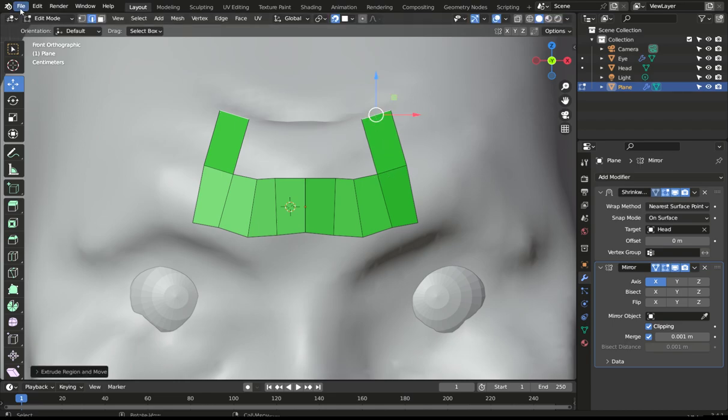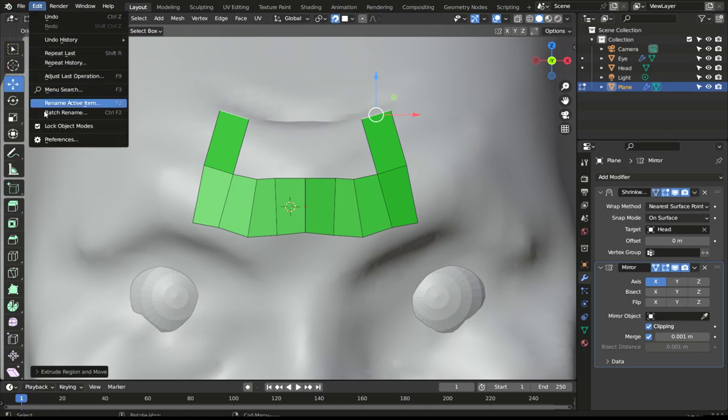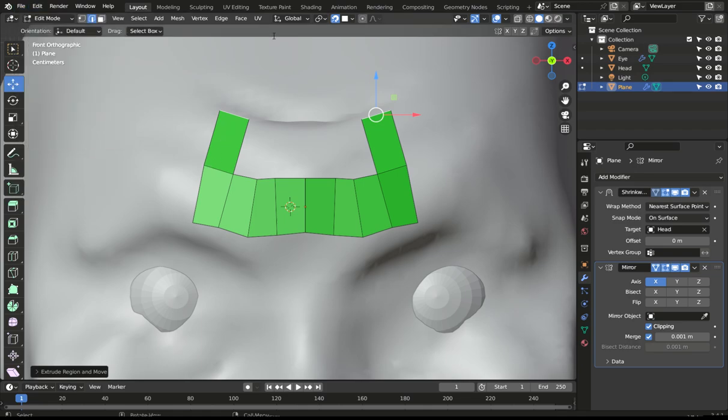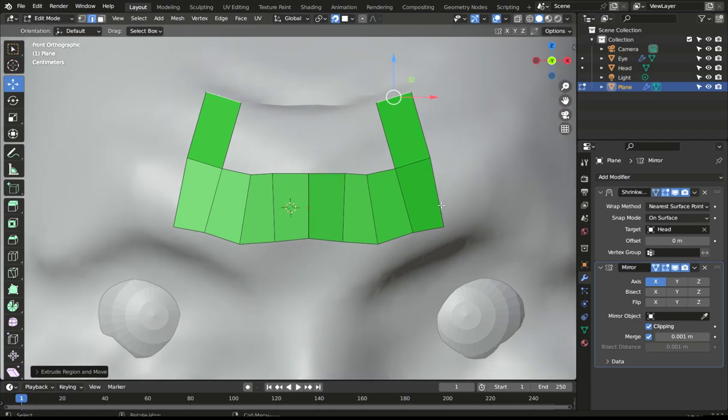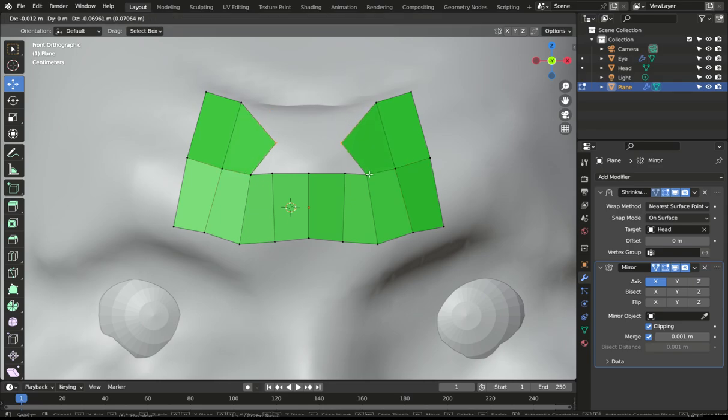And then another add-on that we've installed previously, it's the F2. So go to Preferences, look for F2, make sure that's installed. Great, that's the mesh topology add-on. So the way that that works is go up to Edit Mode, click on your vertice, and if you want to fill a space here, this is a time saver, click on the nearest corner, toggle your cursor here, hit F, just like so.